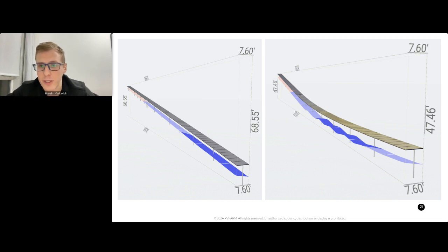Another limitation is the bay-to-bay slope change, basically the slope change on top of each pile, which shouldn't be more than a certain number. Let me take an industry average number like 1.5%. So if you have the first bay at 10% and the second one at 11.5, you're all good. But if you have the first one at 10 and the second one at 15, it's not okay. It's not working. Then some manufacturers also have limitations about cumulative slope change, meaning that if you have a motor, let's say in the middle of your tracker, the cumulative, which is the total slope change on top of each pile, shouldn't be more than a certain number. Let's say, to give you an industry standard, 7% or 6%, something like that. So that's the main difference.